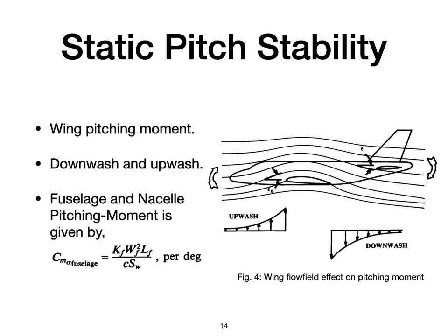Behind the wing, the flow has an initial downward direction, theoretically equal to the wing angle of attack. This downward angle diminishes aft of the wing to a value of approximately half the wing angle of attack at the tail of a typical aircraft. Also, the downwash varies across the span and approaches zero near the wingtip.